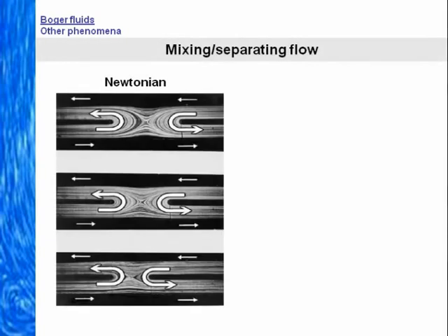In so-called combined mixing separating flow, where the arrows indicate the direction and strength of the flows in the various arms, Newtonian fluids permit easily generated symmetric pictures, with a strong indication of a preference for reversed flow around the obtrusions rather than unidirectional flow in the horizontal directions.